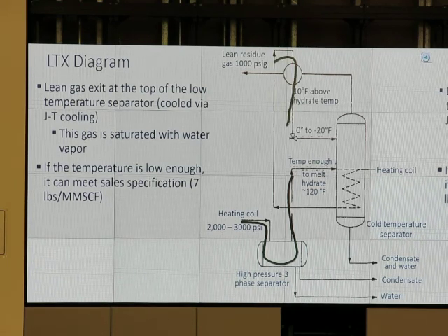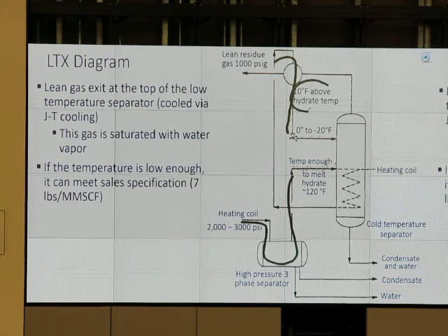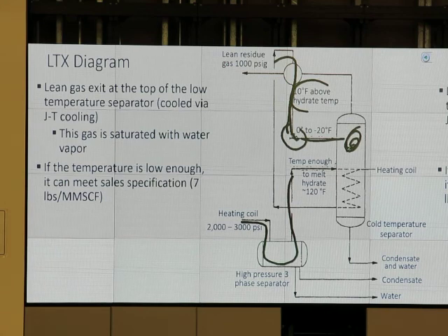When it's before the choke, it is above the hydrate temperature, right? But when it goes through the choke, the temperature drops, and we have hydrate. So the hydrate in the gas is falling down, but because of heat from that thing, heat of itself is used to melt it, so it doesn't plug.